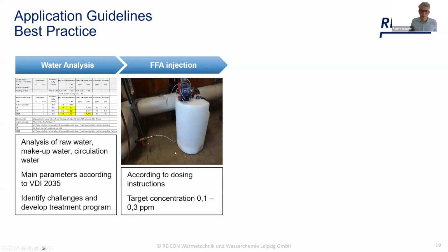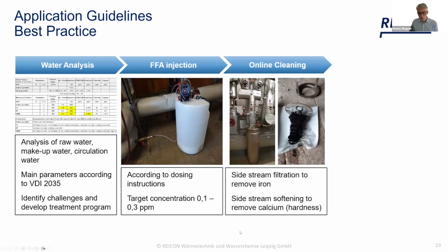Often we use standard dosing tanks, and here you can see the small timer with the plug. So the pump goes on for an hour, stops for 2 or 3 hours, and then restarts again. So we can build up the concentration in the system slowly.